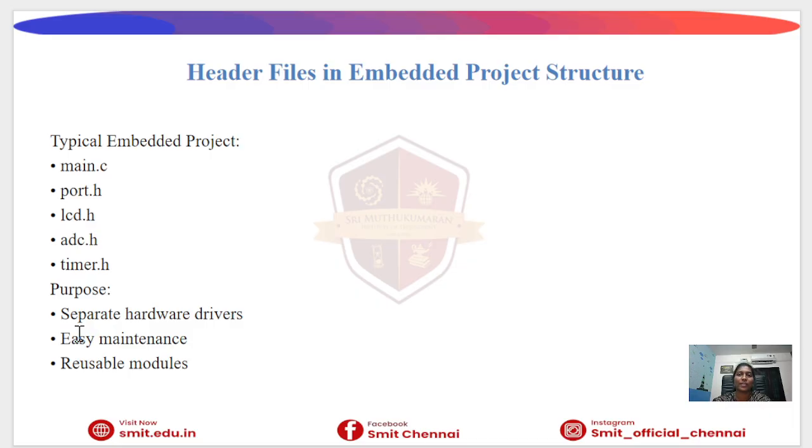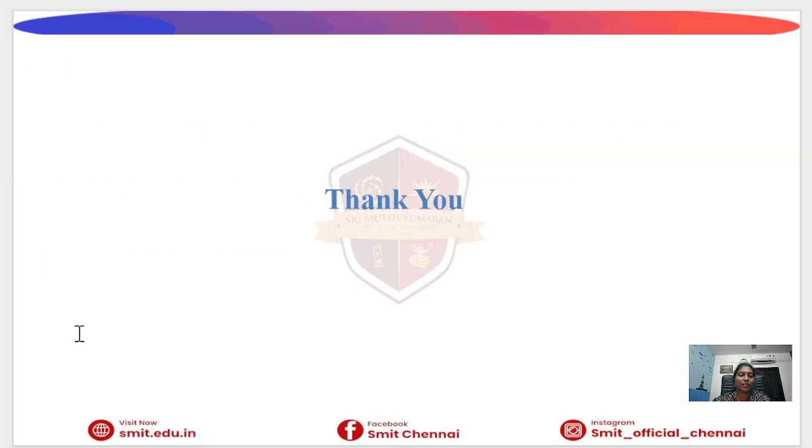So in today's class, we have discussed what header files are and why they are important, types of header files, and port control in embedded systems, in the 8051 microcontroller, and how the ports are connected. In the next class, we will implement a simple LED blinking program using port registers. These are the references, and thank you.